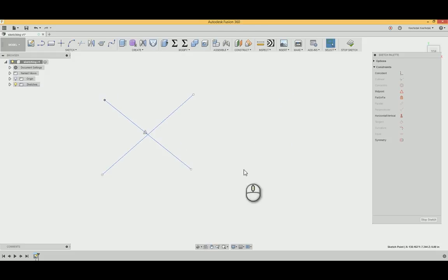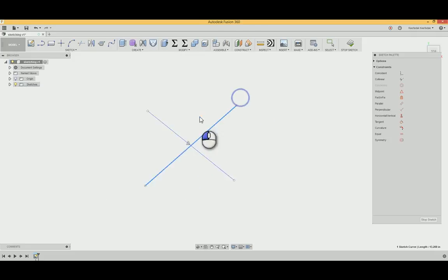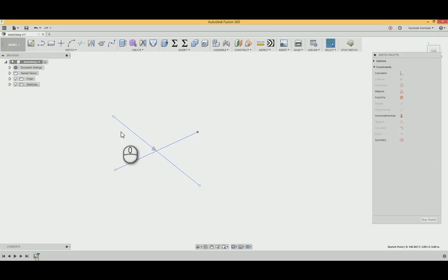That brings us to the next constraint, because do you notice this thing just kind of floats around in free space when you're sketching, and we're going to see this pretty soon when we move on to modeling something. Notice the lines are blue. That means those lines are not what we call fully constrained. They still have some degree of freedom that they can move or bend to. And if you're designing something, you don't want any blue lines on your finished sketch. They're going to turn black. There are different ways to do that, but we'll get to that.